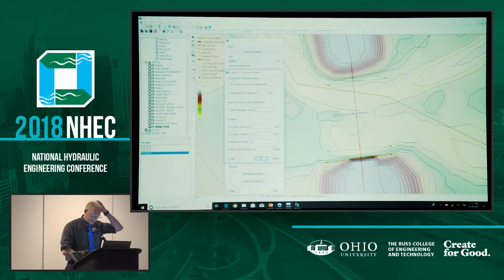And then the rest of this, Hydraulic Toolbox asks for these variables in several different places. Rather than have to go through and change them consistently each time, you can come in here and change them in one spot, and it'll update all of those variables for you when you bring it up. So if you're working with just slightly changed variables, you can make that change.